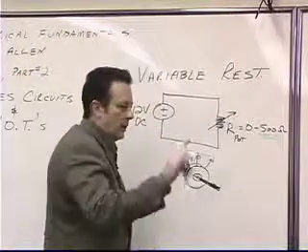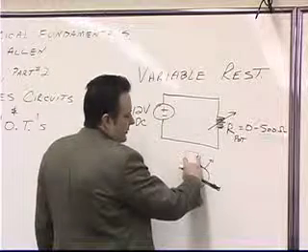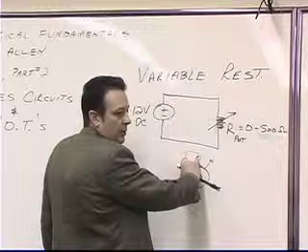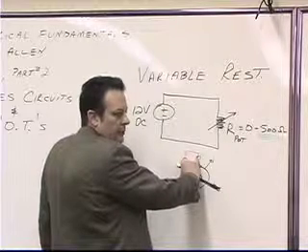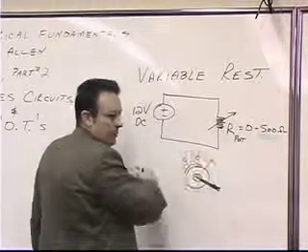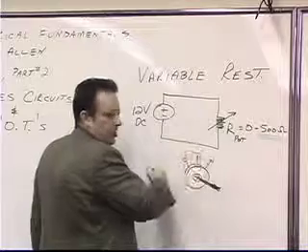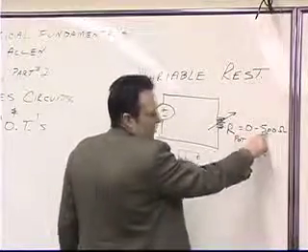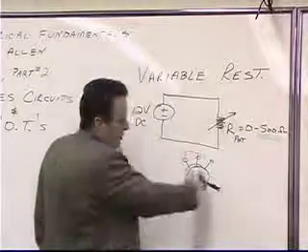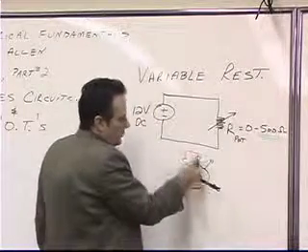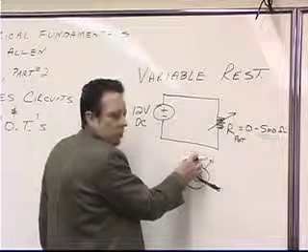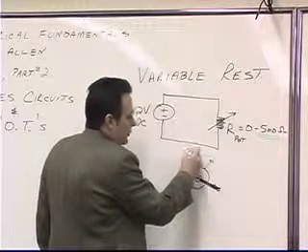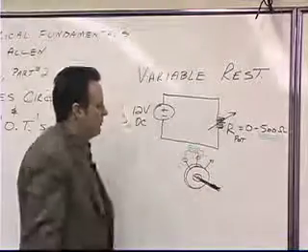Okay? On the other hand, if you connect the center post of the potentiometer and the outermost left post of the potentiometer, you're going to be getting one extreme, either the low side or the high side. So let's say that this can go from 0 to 500 ohms. And let's say that you had turned the knob so that the resistance between these 2 posts right here measured 50 ohms.